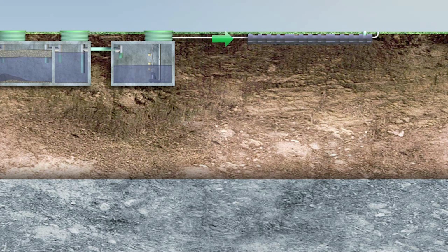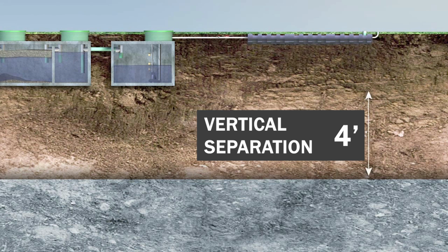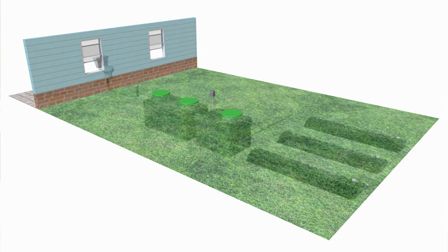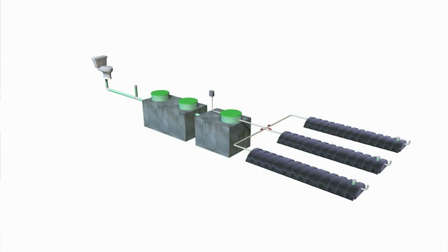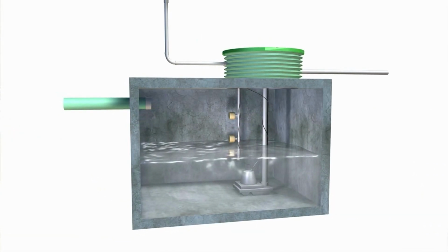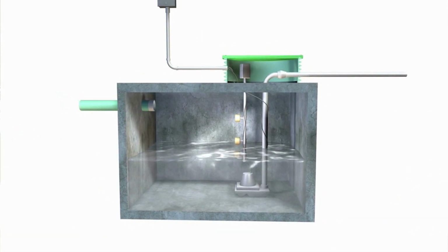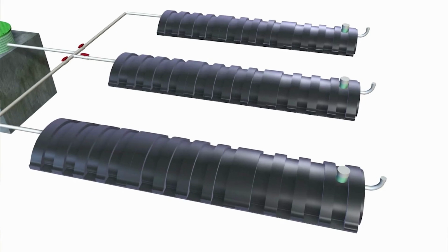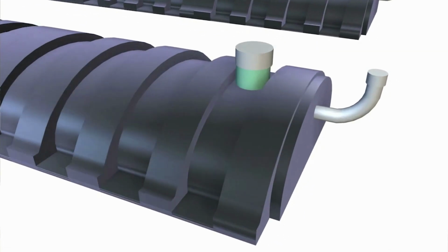Pressurized systems may be used where sufficient soil is present, but the wastewater needs to be pumped to a certain area of the property. Pressure systems are also used when the soil type requires a specific dosing or when soil has limited permeability. Pressurized systems typically start with a septic tank, just like a gravity system. After the septic tank, the wastewater flows into a pump tank and is then pumped to the drain field where it's spread equally throughout the drain field lines.